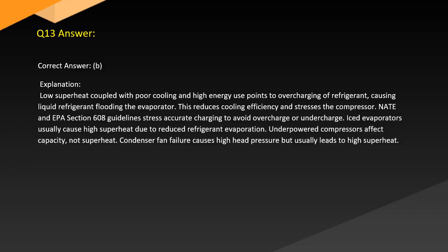Answer. Correct answer: B. Explanation. Low superheat coupled with poor cooling and high energy use points to overcharging of refrigerant, causing liquid refrigerant to flood the evaporator. This reduces cooling efficiency and stresses the compressor. NATE and EPA Section 608 guidelines stress accurate charging to avoid overcharge or undercharge.